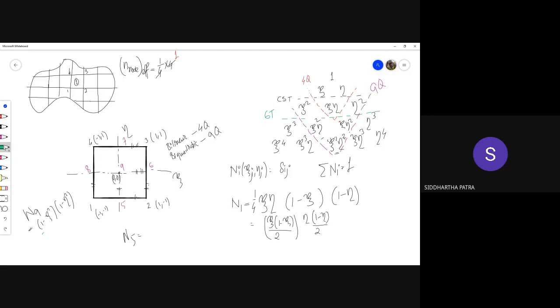if I take a 9-noded quad element, I'll have node number 5, node number 6, node number 7, and node number 8. And ultimately I'll have node number 9. But let's say I have up to node 8. How are these mid-side nodes shared? How many elements are they shared with?